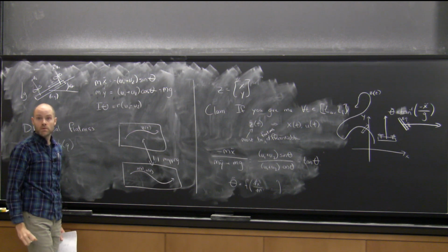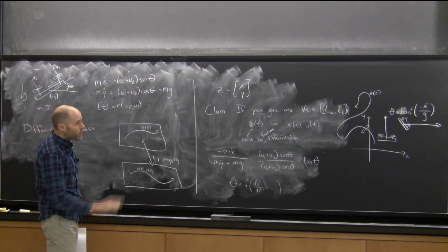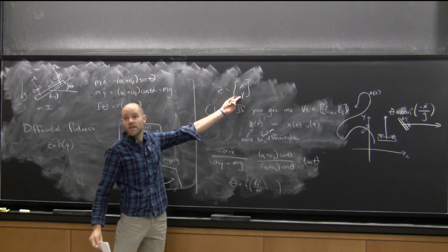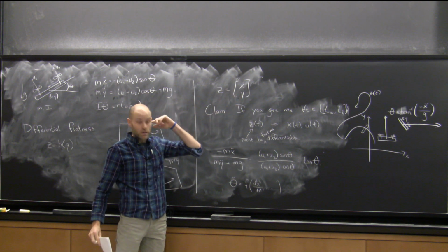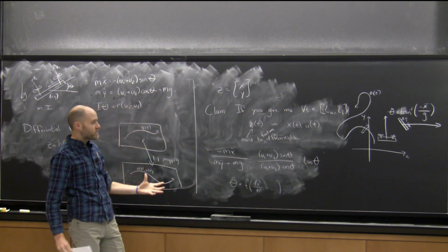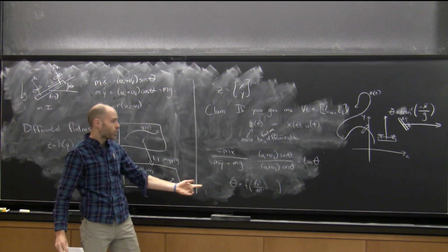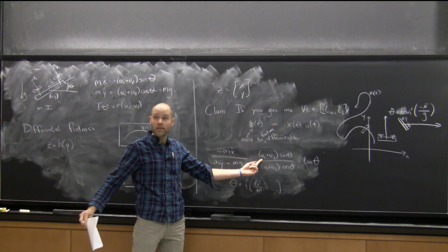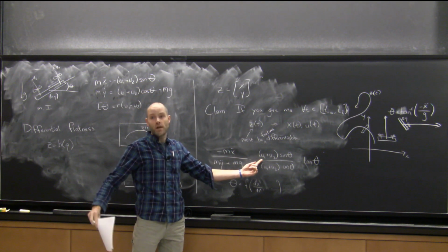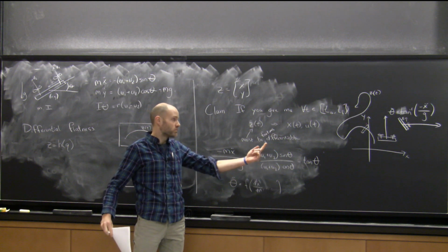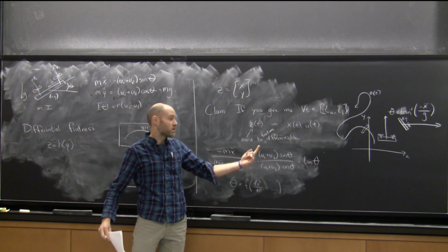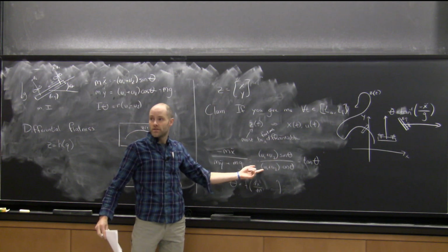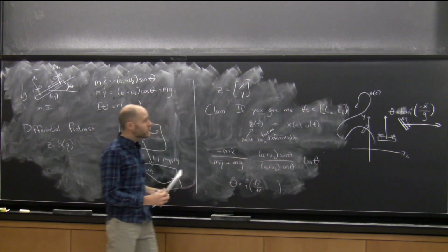Completely. Okay? So knowing z, when this is your choice of z, completely specifies what everything has to be doing on the quadrotor. In practice, this is just telling me that I know what u of t, u as a function of t, should be along that path. There's extra work to stabilize that path, to make sure that if there are small differences in initial conditions, you'll still return. But to just execute the path, this is everything, okay?